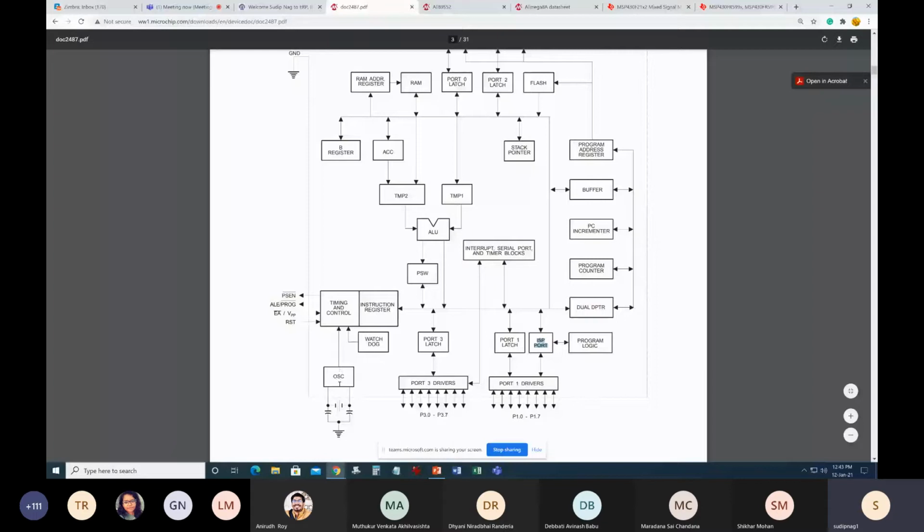It is a digital circuit, so there is a digital oscillator which gives a square wave at the output, and this square wave is distributed by the timing and control. Wherever you need it, like for latches such as D flip-flops, you need a clock signal. That clock signal is not deliberately shown here, but it is controlled from timing and control. So timing and control is one of the hearts of the system, you can say.